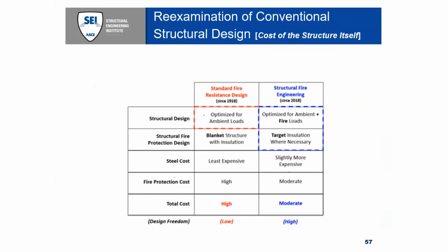Think about the enhancement of the mesh. That has benefits beyond just fire. If you're designing floors to become tensile membranes and you have a bomb blast that takes out a column, you could synergize those designs and have mutually beneficial aspects, but chances are that a structural fire engineered building is going to be more resilient to that, even if not specifically designed. This is not to mention that structural fire protection often represents a major roadblock to design innovations because you're mating a 100-year-old technology with modern construction. Not a good combination in all cases.